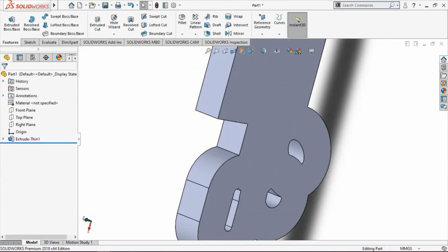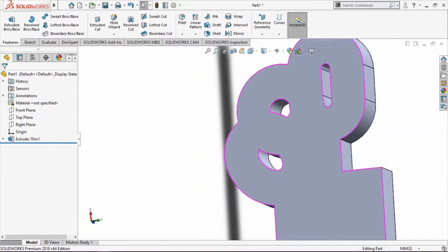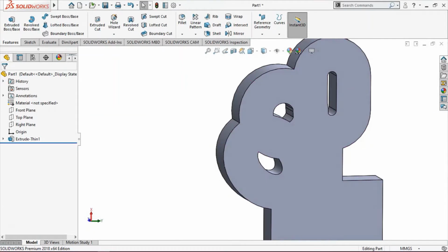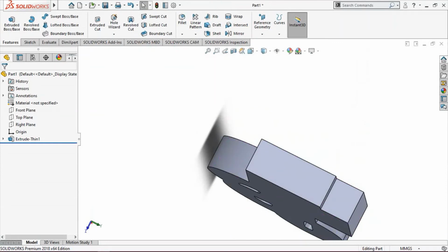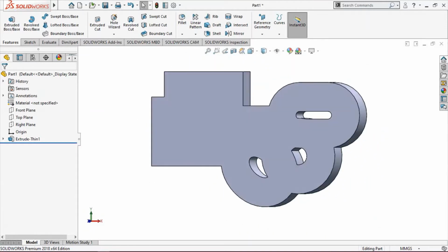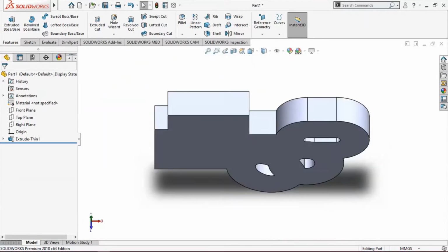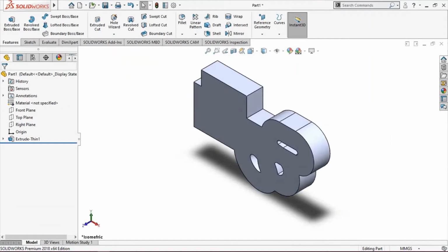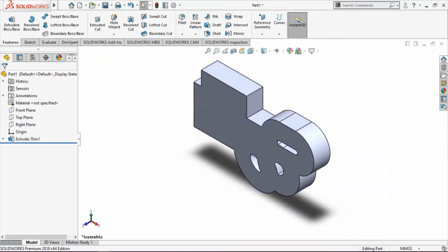Then look, after extrusion, the components have joined, but it takes another shape, which is somehow very strange. By clicking on Ctrl 1, you see this view. On Ctrl 2, Ctrl 3, Ctrl 4, Ctrl 5, Ctrl 6, Ctrl 7 in isometric, and Ctrl 8 for this normal, but better for isometric.